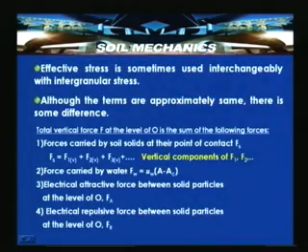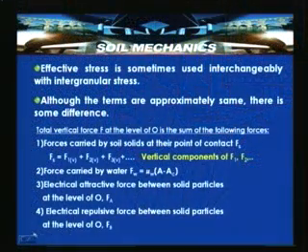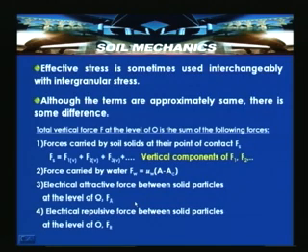The force carried by water is nothing but UW into A minus AC, where A is the total area of the plane under consideration and AC is the contact area. So, FW is equal to UW into A minus AC. Then FA is the electrical attractive force between the solid particles at the level of O, and electrical repulsive force between solid particles at the level of O is FR. So, the total force is a summation of these forces.